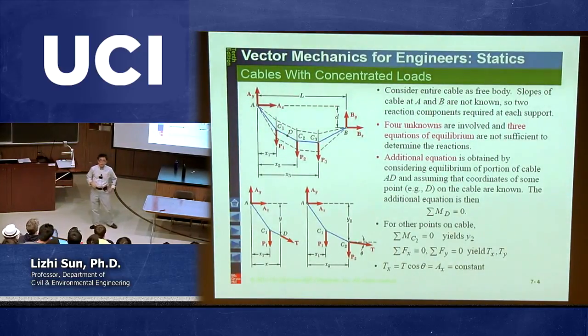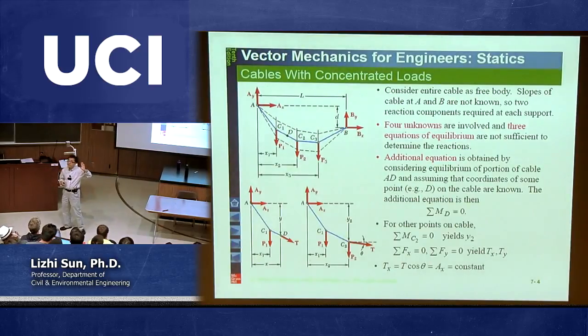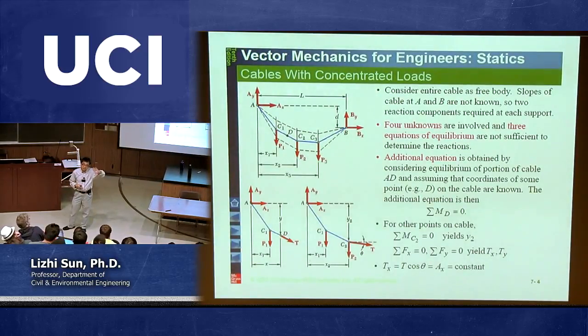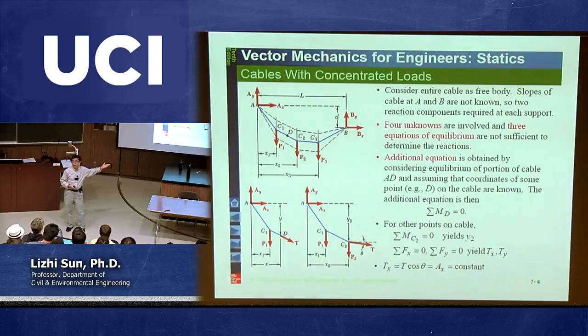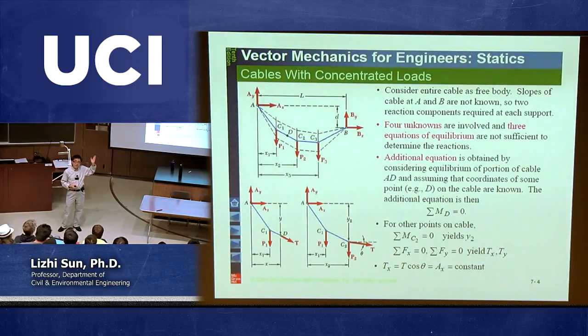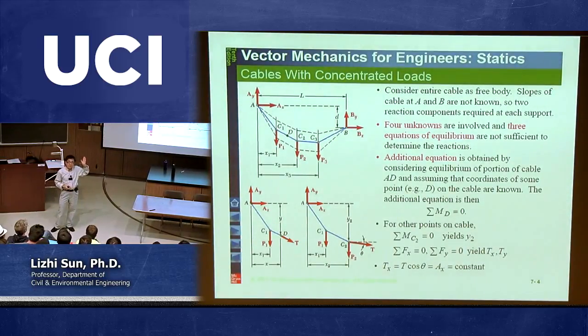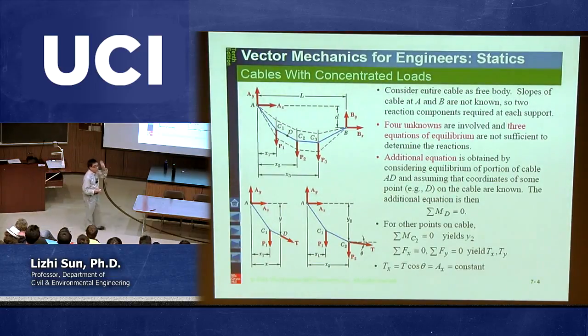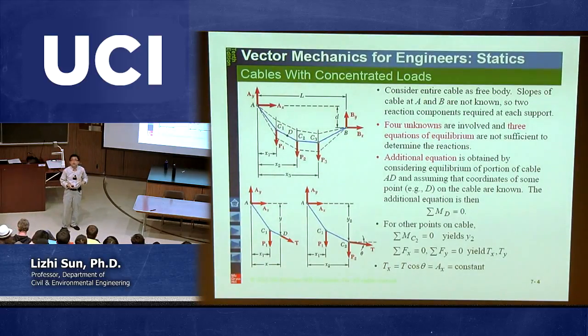If you had encountered this kind of problem before, the simple way you could say is, let's give up, we don't know how to do it. But this time, I'm giving you a trick, because it's specifically for cables. It does not work for beams. For cables, you can in fact generate another equation. And that's also the special case we talked about before in chapter 4. That's called the two-force body problem, in fact.